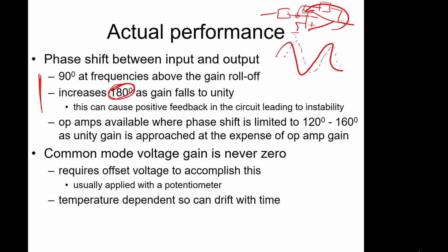So phase shift usually isn't a problem. However, if you're getting 180-degree phase shift, and that's when you're trying to go at higher frequencies at high gain, you start getting these phase shift problems, and it can lead to instability in your circuit. So not something to worry about in this module. We won't be pushing our circuits that hard, but again, something to think about with more specialized circuits.